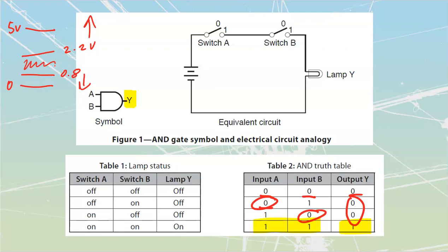But what we'll do running into one of these things is, as long as we provide at least 2.2 volts, let's call that 4 volts. We have 4 volts on that one, and if we have another 4 volts on this one, we are going to get 4 volts out over here. It does not add voltages together. It just means that it puts out the same level as what the other ones were. So this one over here is going to be defined off of this truth table.